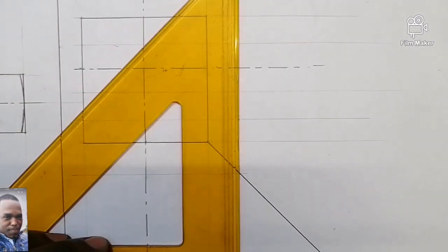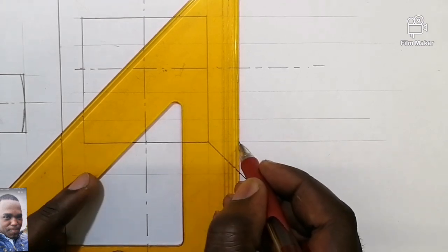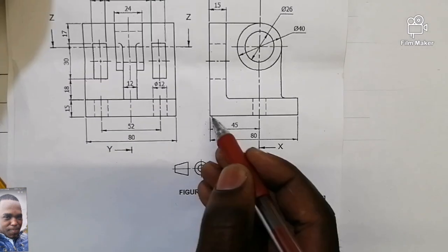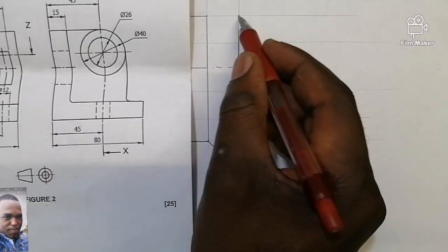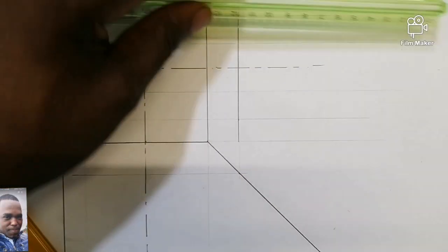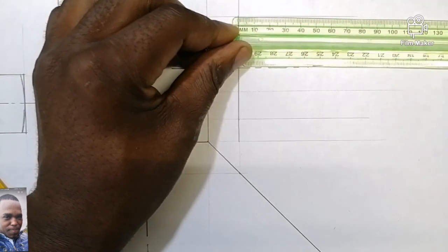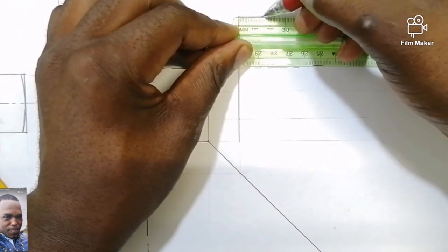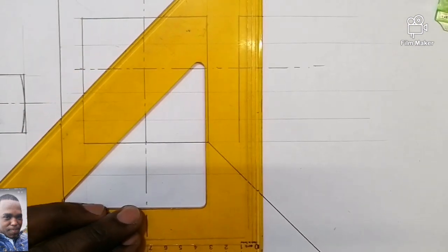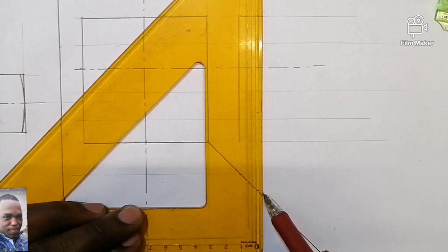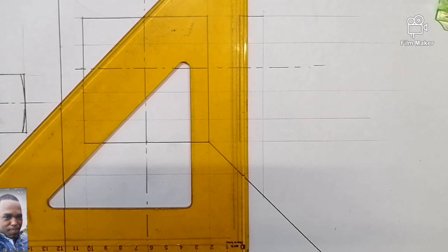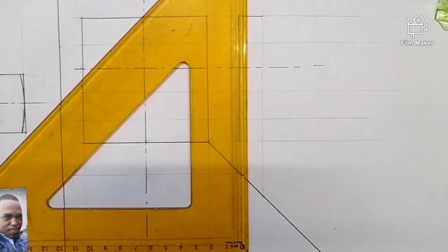So which means now without fear or favor, I can have this line solid. Which one is this one? Is this one from there till there? Then from here till there is 15 millimeter, isn't it? Which means it's this one. Do it simple, eh? Then construct it down, till the line that you just drew, that is at an angle of 45 degrees. You understand? Like this.